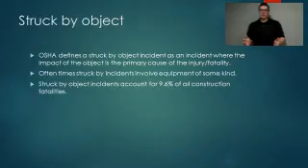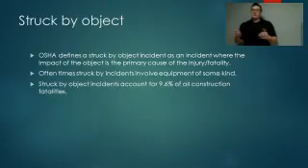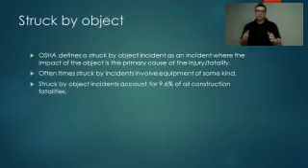The second category within OSHA's emphasis program for the Focus 4 is struck by object. And OSHA defines a struck by object incident as any incident where the primary cause of the injury or fatality was from that struck by object. A lot of struck by object incidents involve heavy equipment or heavy machinery, and so a lot of the controls that they use or ways that we mitigate this hazard involve things like heavy equipment.